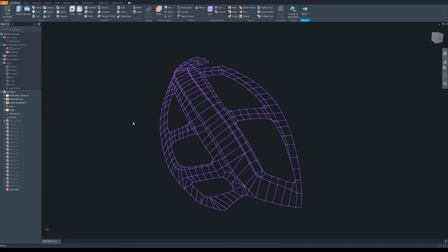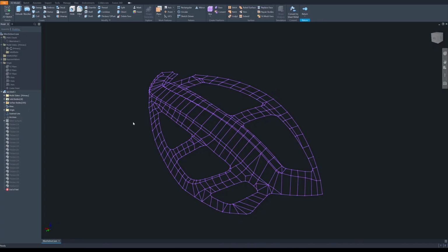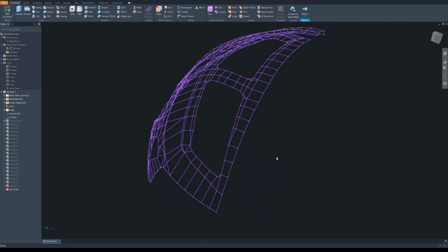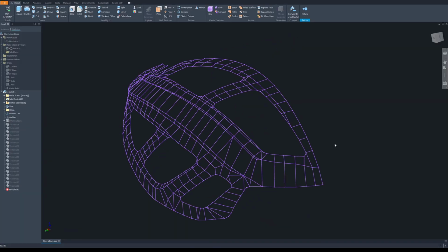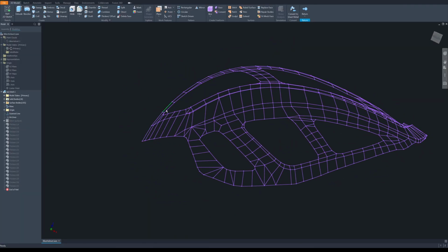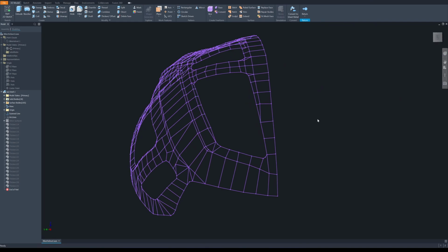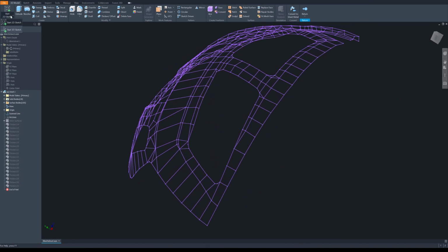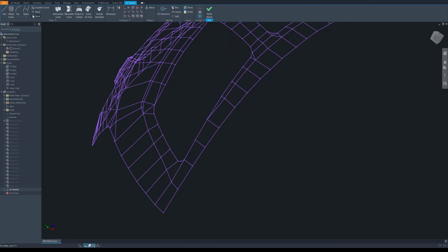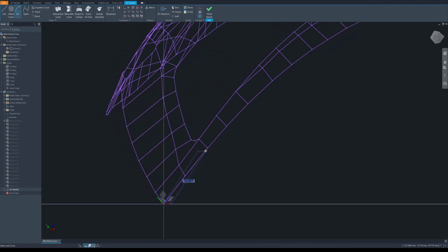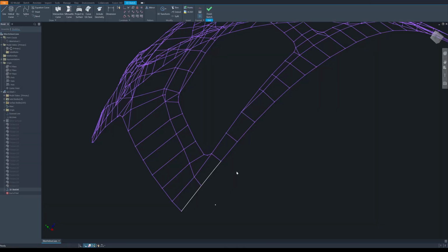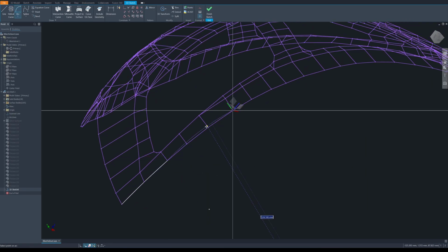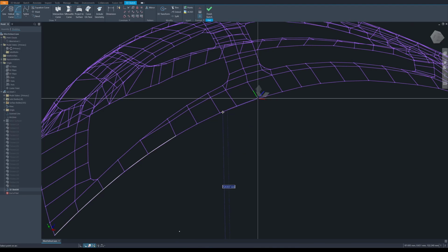Okay, here's 3D lines that I import from the Blender directly into the Autodesk Inventor. Next step, I will have to create an arc, because this one is a straight line, it's a segment line, but what I need is a smooth curve and the arc to create a surface. So I will make a new 3D sketch, and with this 3D sketch, I can snap it onto the polyline that I import from the Blender. So I just keep making the arc line. It doesn't have to be a small segment, can be larger like this.